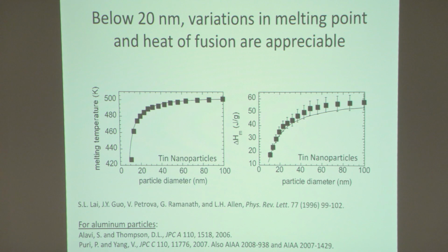So if I have a small aluminum particle, I'll see the same characteristics, and it'll also be true with regards to aluminum oxide. Now, I mentioned one of the problems was the lower sintering temperatures. So you can imagine now if I have nanoparticles in a matrix of a binder and they're in close proximity, as the thermal wave starts propagating down into the material, the temperatures for sintering are lower. So if the nanoparticles start to sinter, then I'm losing surface area, okay? And I'm starting to approach, again, a micron-type behavior versus a nanoparticle behavior.